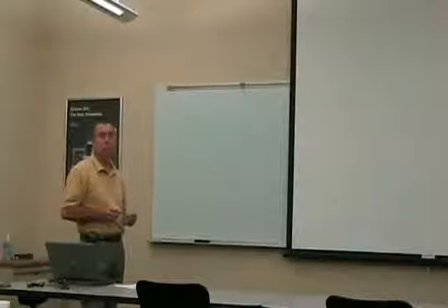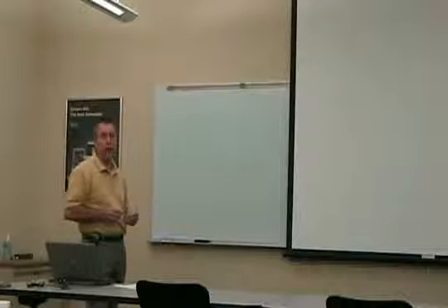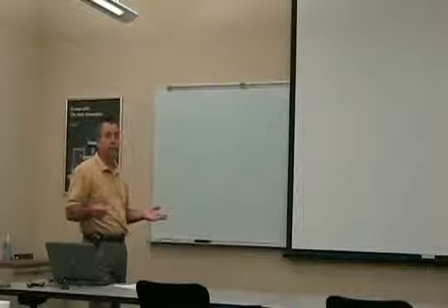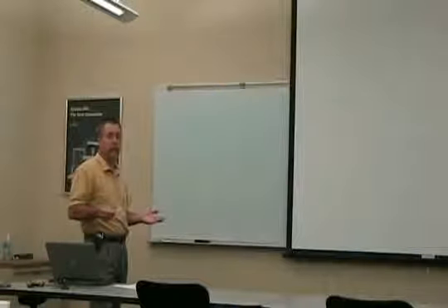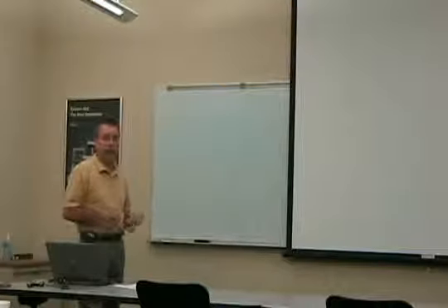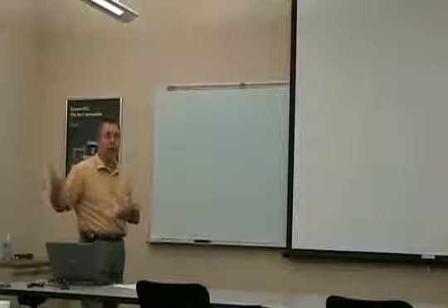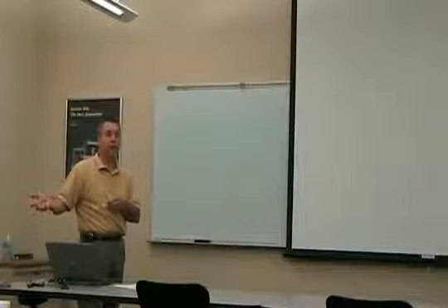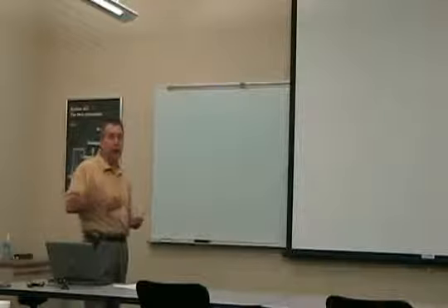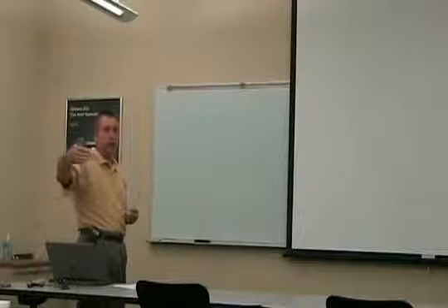Steve, the difference between the load and the connected load, again? Well, my load is what I calculate, and my connected load is actually the equipment that I'm putting in. For instance, this room might be 2.3 tons, but I've got to put a 3-ton or 3.5-ton heat pump in it because I don't have a 2.3-ton heat pump. And that just multiplies as you go through the building.